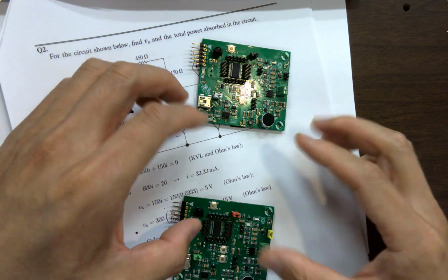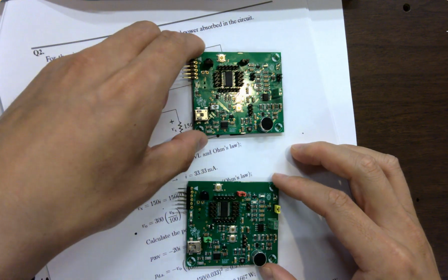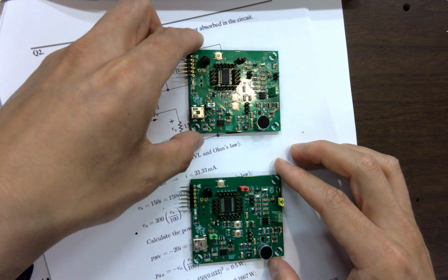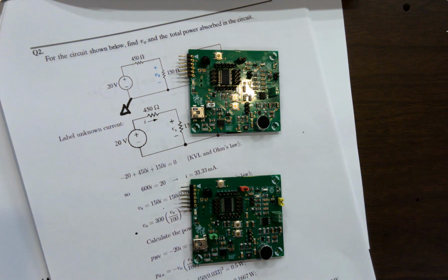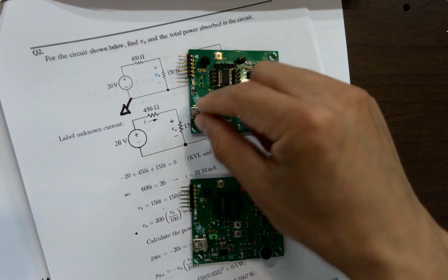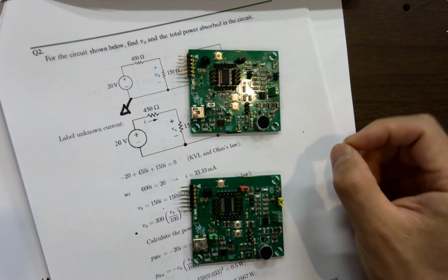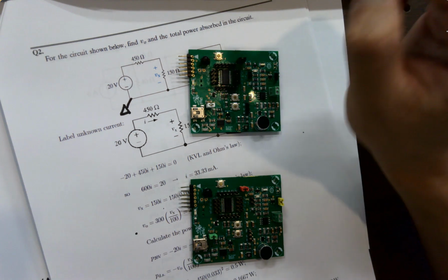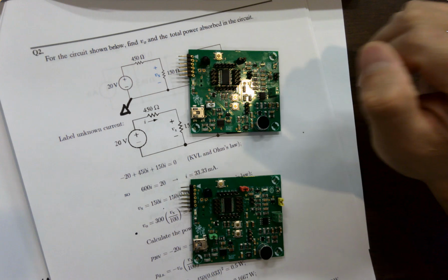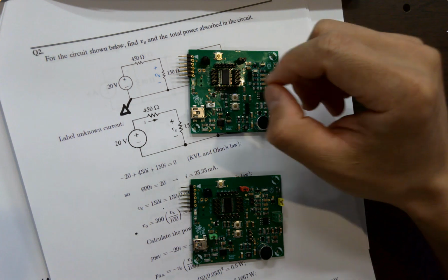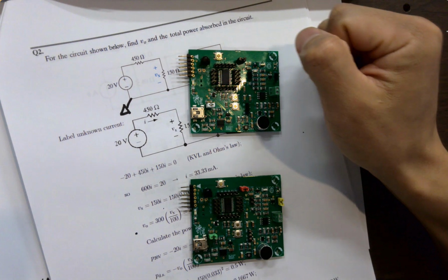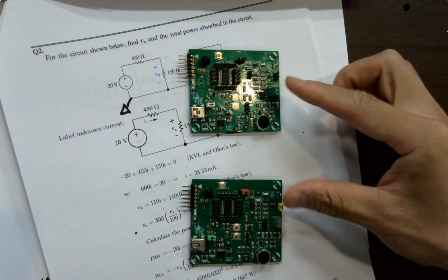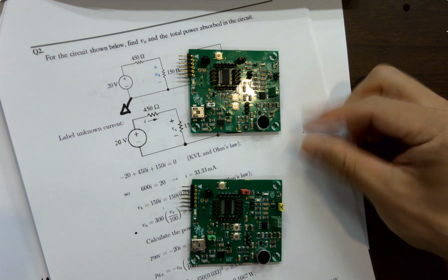That's a very common issue of student design. I've seen this issue 100 times, and 80% of the chances is the missing of common ground. Whenever I start debugging a circuit for students, anywhere, anytime, the first thing I check is if there's a common ground, because 80% of the problems is the missing of common ground line. Keep that in mind. So you have to find out the ground line, short it, just have a common ground so they know what is 0.